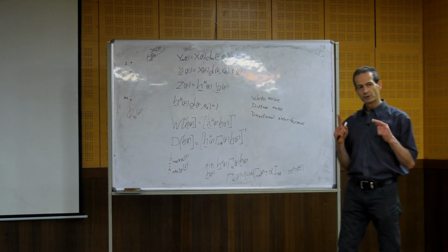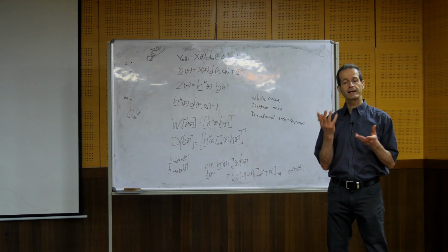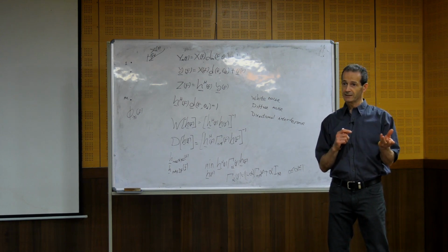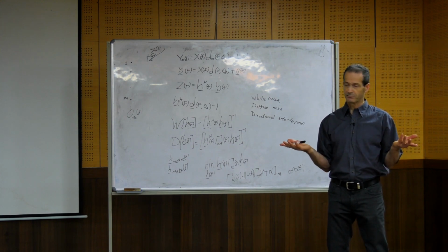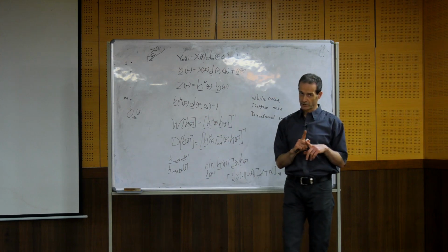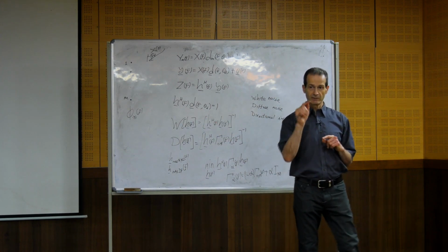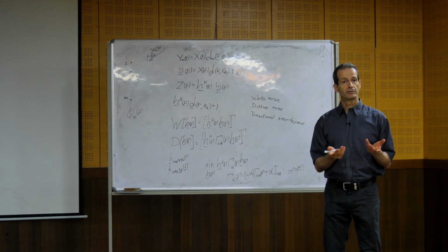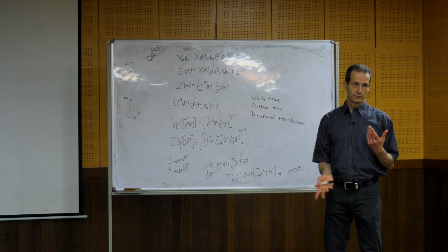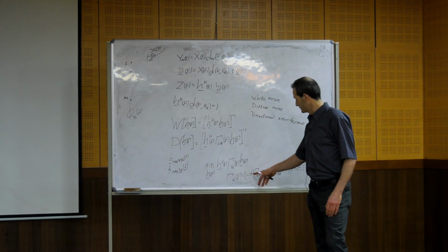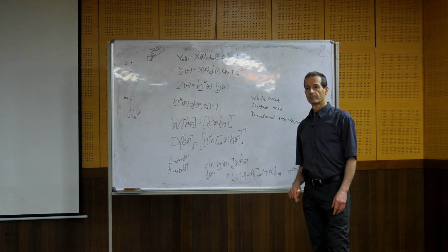So you see, with the multi-channel signal enhancement, we had a trade-off between noise reduction and signal distortion. Here, we don't have such a trade-off because we have this constraint, so we don't allow any distortion. Even without this distortion, we have a different type of trade-off between white noise gain and directivity factor using this kind of parameter.